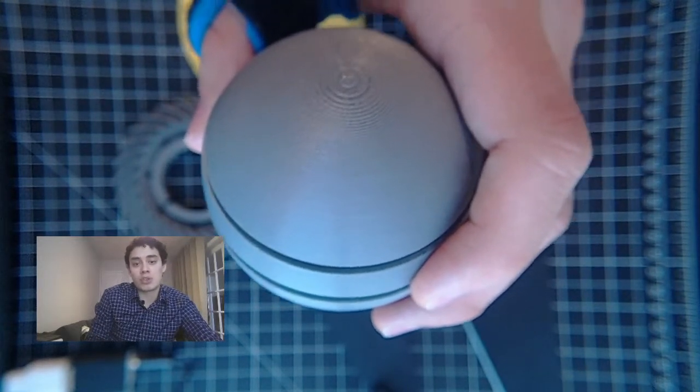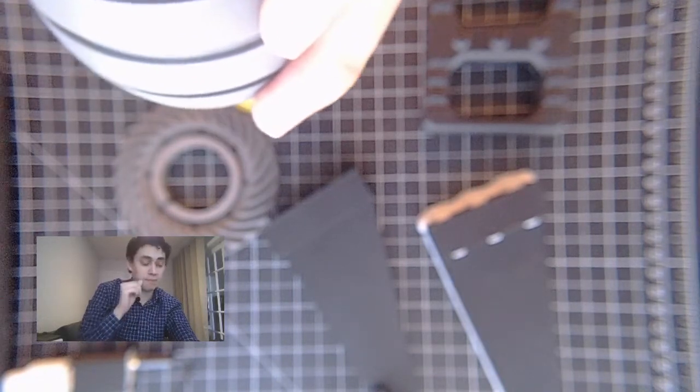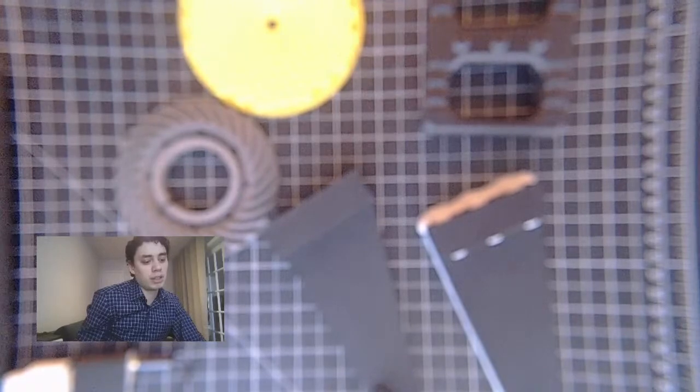What causes over extrusion? Overextrusion is caused by the extruder actually pushing more material than the build plate or the part is actually able to retain, right? Which means I'm moving the extruder at a slower speed than the speed that the material is flowing in, right? So essentially sort of like saturating the material out and causing it to spill over. I don't have a good part to show that.